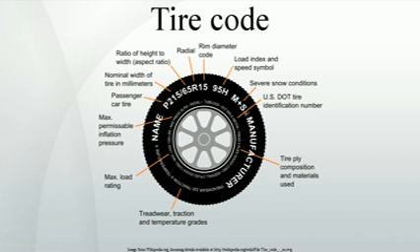If a tire size has three sets of numbers, 15x6.00-6, 26x12.00-12, 31x15.50-15, the first number, 26x12.00-12, is the approximate height in inches. The second number, 26x12.00-12, is the approximate width in inches, and the third number, 26x12.00-12, is the rim diameter in inches.